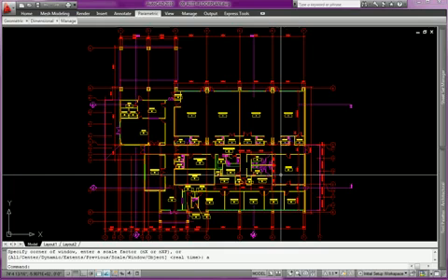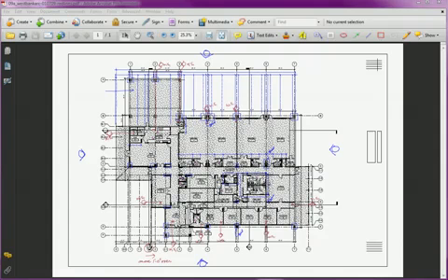Revit defaults to the AIA standard layering system, but can be modified to any layering settings required by the architect and/or consultants. Adobe Acrobat or Autodesk's Design Review can be used to mark up images of the sheets. The markups in red are wall section keys submitted to the architect for approval. The blue markups are made by the CAD production team, and the architect is not involved in these processes.